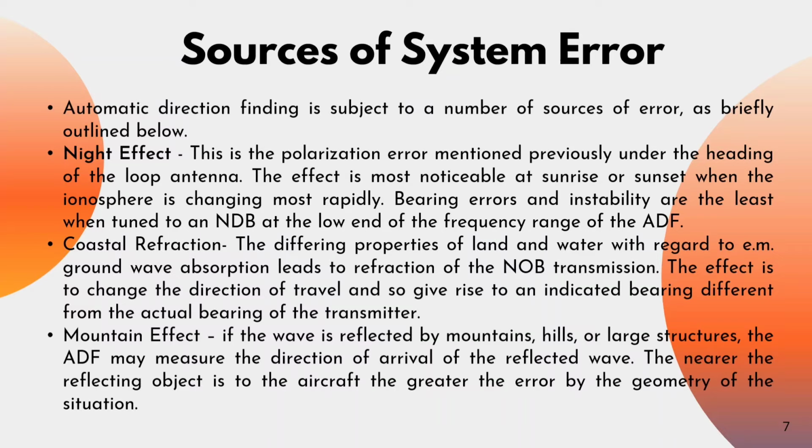Mountain effect. If the wave is reflected by mountains, hills or large structures, the ADF may measure the direction of arrival of the reflected wave. The nearer the reflecting object is to the aircraft, the greater the error by the geometry of the situation.